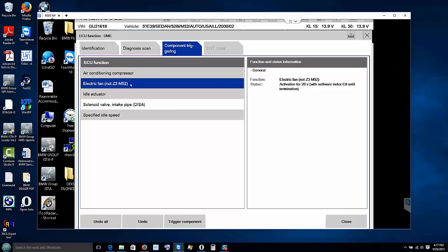And all you have to do now is find a way to calibrate whatever you need to calibrate and then remove the fault code and so on. Usually when you buy a DME, the VIN number is already put into it by the dealer, and then you plug it up, program and code it, and then you're good to go.